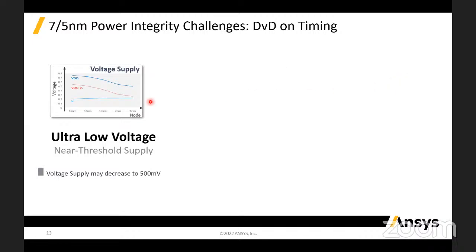The first diagram shows the supply voltage trend. As we move to advanced technology nodes, we are reducing the supply voltage on our designs. As you may remember from our CMOS basics, power is proportional to the square of the supply voltage. So lowering the supply voltage yields significant power savings. Over the last few years, the industry has moved from supply voltages in the range of 1.8 volts or 2 volts towards 1 volt or lower for 7 nanometer nodes.